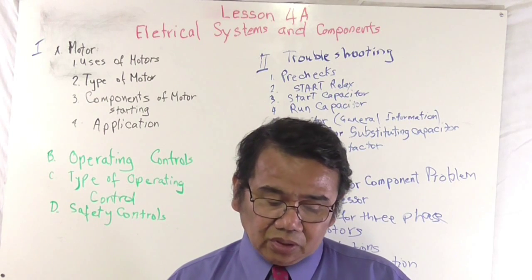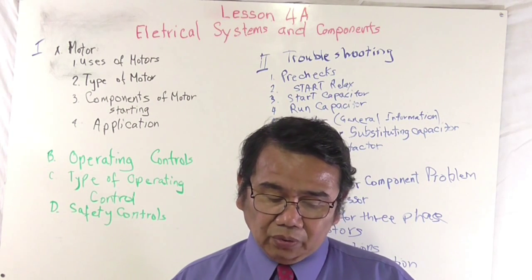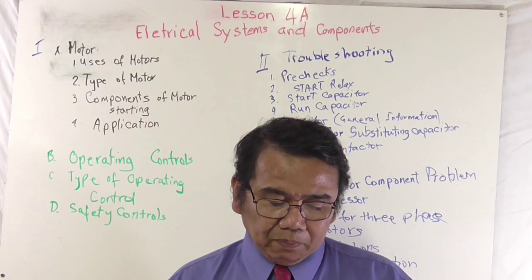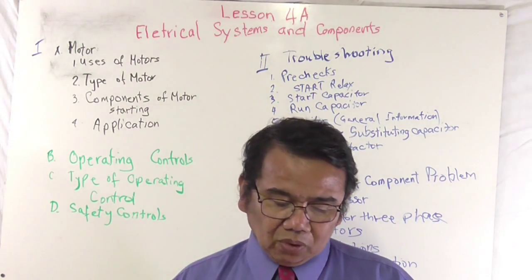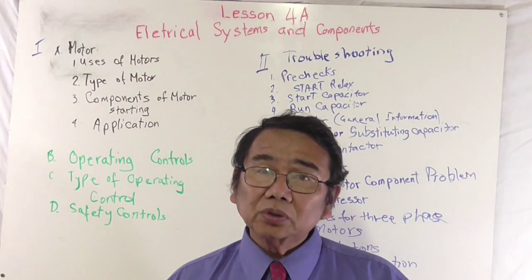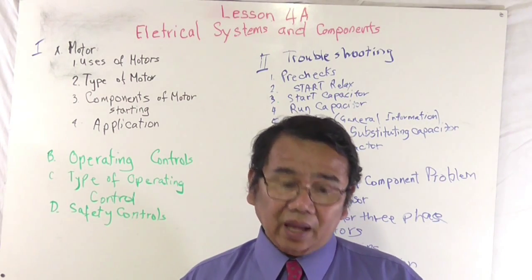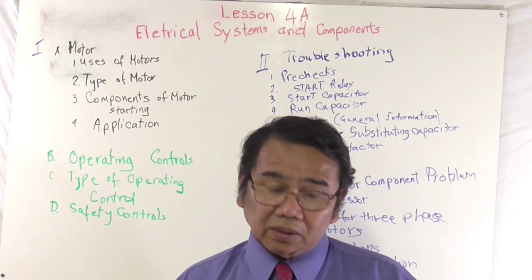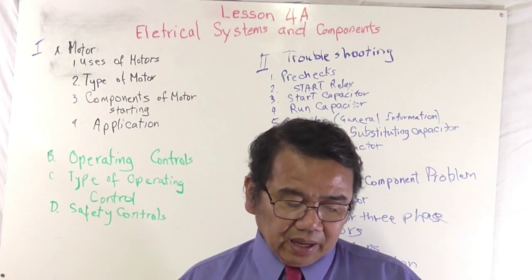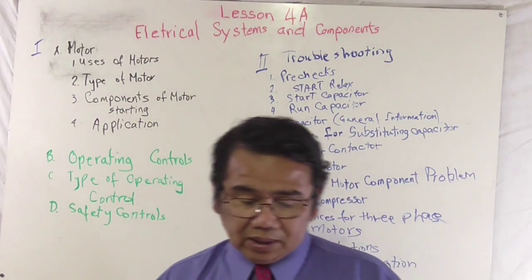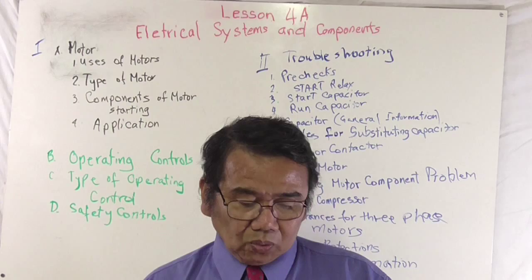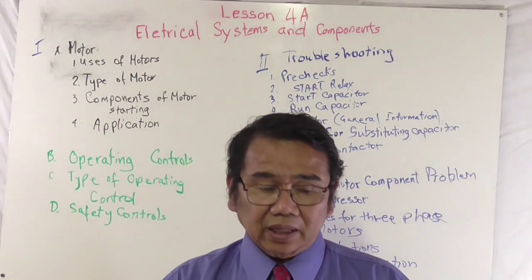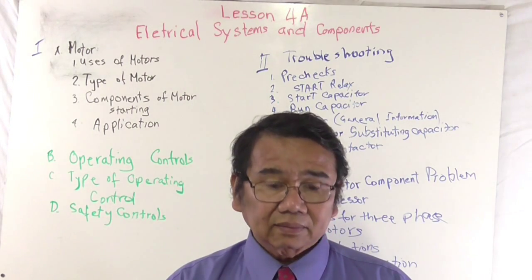Terminals are marked as H or COMP for compressor, F for fan, and C for capacitor, common to both H and F. H is wired to the compressor start terminal. F is wired to the fan motor start terminal. C is wired to the run terminal of both the compressor and the fan.